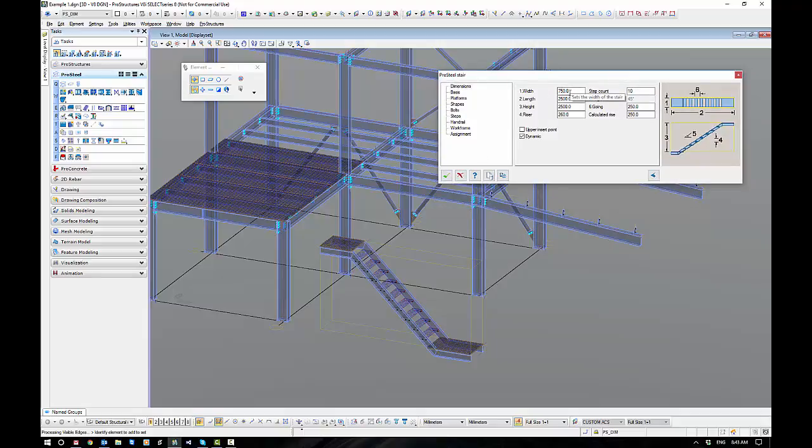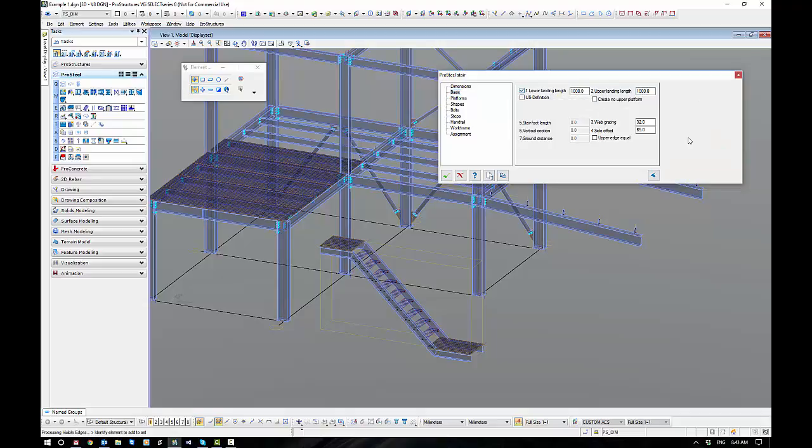Within here I can set up the boundaries of the object, so this wide, this long, this high, and just flesh out the basis of it. But before I even go to that, I kick off here. Do you want a bottom landing, or do you want to take it straight to a slab on the ground? They're really our two options, whether we go from the ground up to a support member or from a support member to a support member, because this is really how we run in Australia.